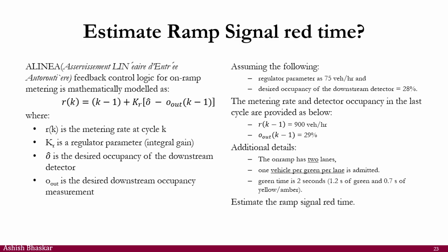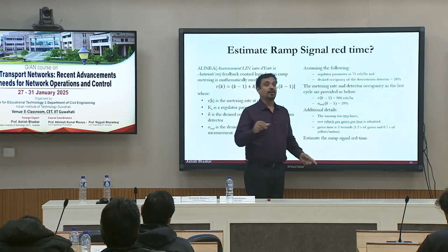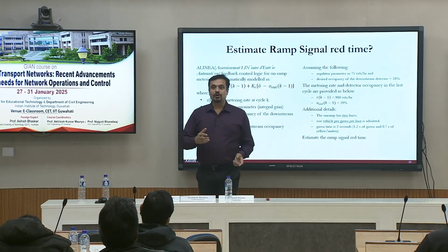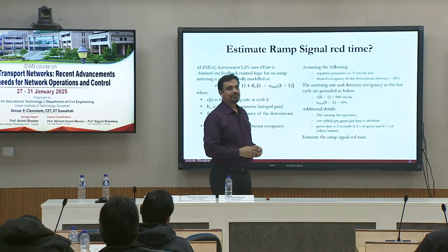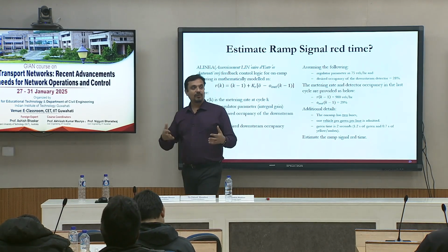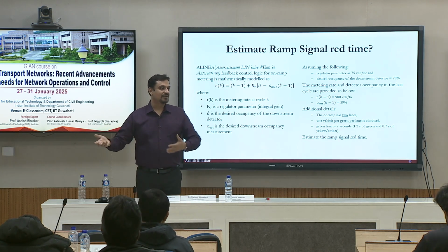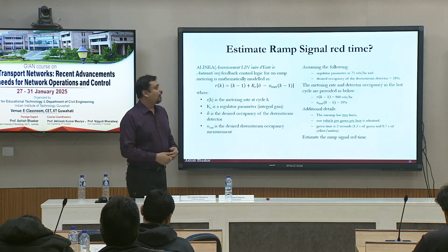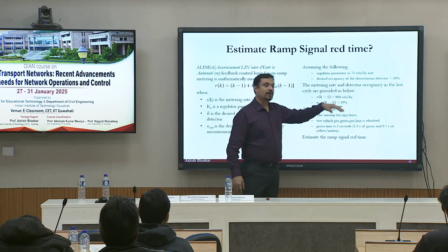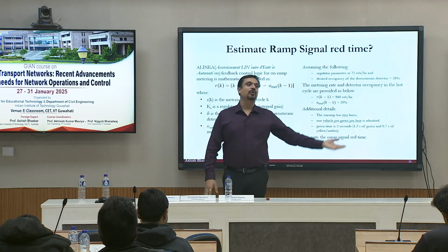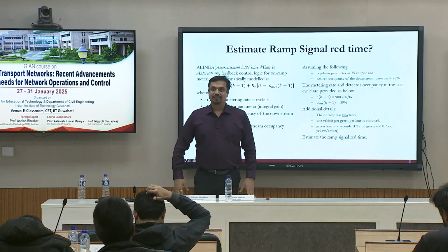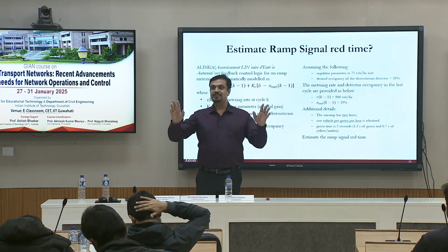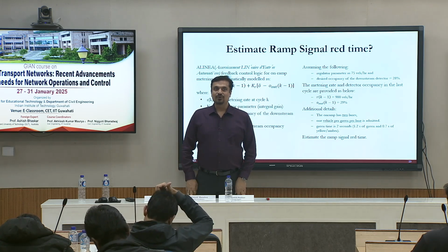No, the difference is now you have one vehicle per green per lane and you have two lanes of the on-ramp. So earlier I only talked about there is only one lane on-ramp. Now I'm saying that there are two lane on-ramp. The concept here is you have to increase the headway. You have to make it twice. Yeah. Or you can convert your flow rate to per lane, and then naturally you are going to get a headway per lane. So either way you should be fine. Are you fine with this? Yes or no?